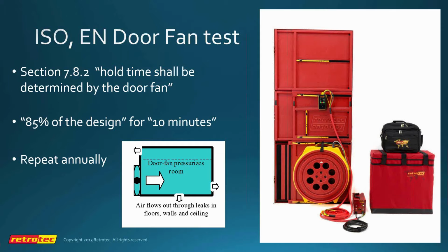The ISO standard also requires that you hold your minimum concentration up to 90% of the enclosure height, which is another huge difference, which tends to make the enclosures extremely tight. So those are the fundamental differences. The rest of the material that I'm going to run through is going to be pretty much the same. And if I have time, I'll whip over to my NFPA presentation and show you a few extra slides that relate specifically to NFPA.